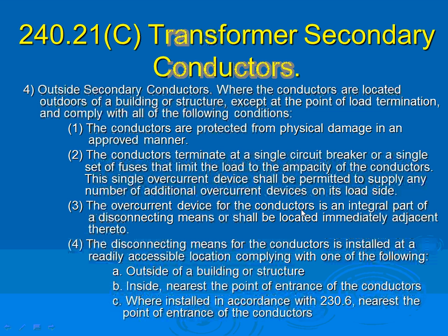Okay, so that covers transformer secondary conductors inside the building. Everything you've seen is inside the building. Now what happens if I want to tap a conductor outside the building? The limit is the sky. Who cares? Remember that the National Electrical Code is written by firefighters, guys. If you have fire outside, up in the air, it's not as dangerous to the building as if it's inside. So really, the rules relax when you go outside the building. You're not burning the building. You're not trapping people in a burning building.